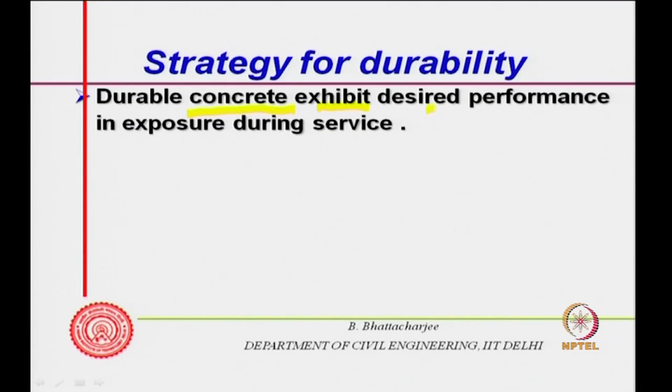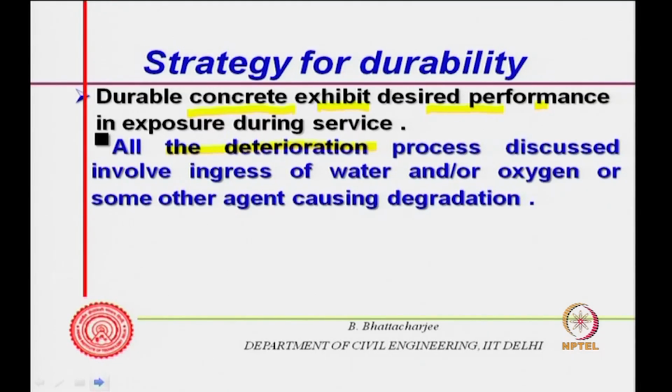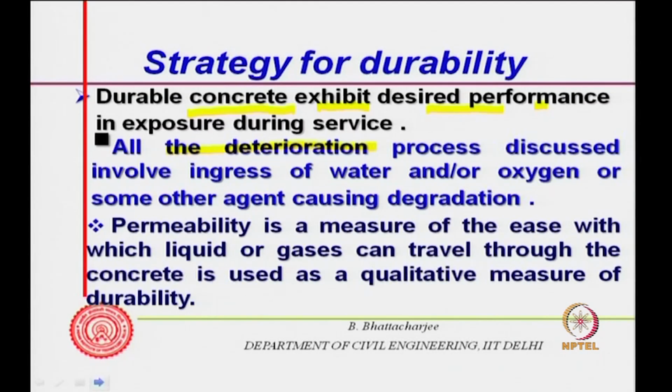Durable concrete must exhibit desired performance in exposure during service, that is what we said in the beginning. And in all the deterioration processes that we have discussed, we have seen that they involve ingress of water or oxygen or carbon dioxide or chloride or some agent causing degradation. So, since we can't address specific degradation phenomena, what people have done earlier is that permeability has been considered.